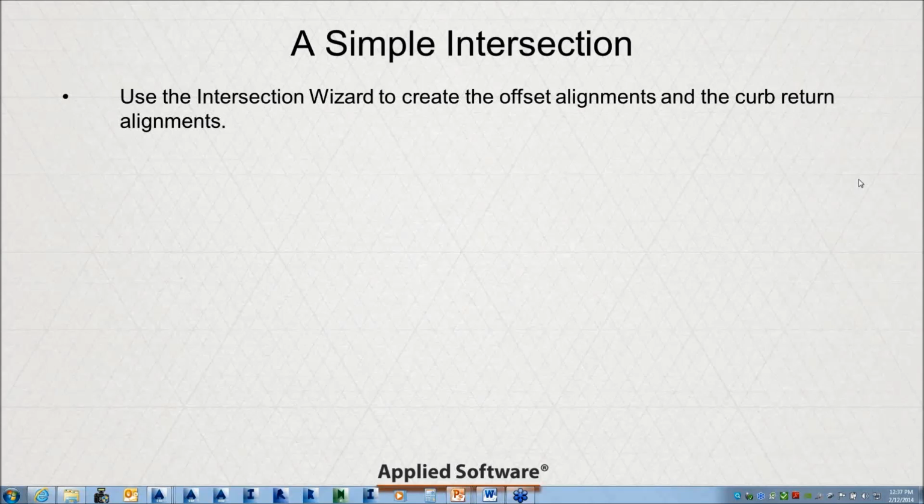Secondly, if you wanted to add superelevation data to those curve returns, you have to keep that in mind. Superelevations typically run along curves, so keep that in mind. Curve returns typically are the radiuses of the curve, so you want to keep that in mind also. And then building an assembly with just a generic link. We're going to run through that just to represent our roadway. And then also adding baseline and regions to our corridor. So really we want to collectively put all the pieces together.